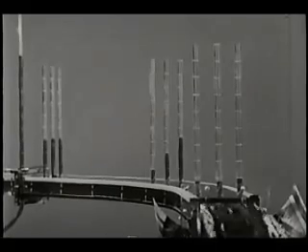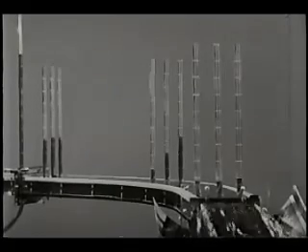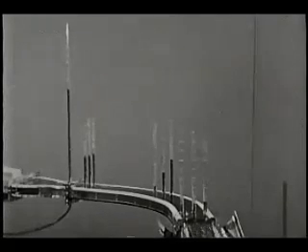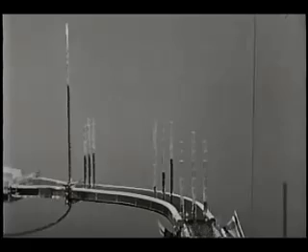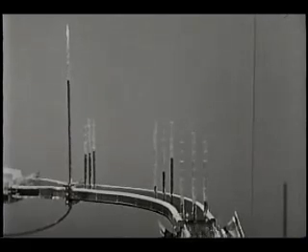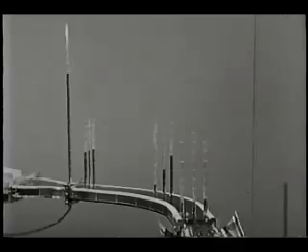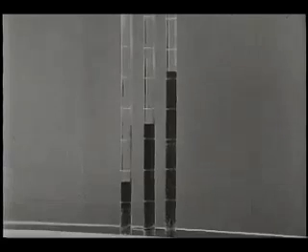This tall tube shows the stagnation pressure in the large upstream settling tank. The difference between this stagnation pressure and the static pressure at the upstream tubes gives a dynamic pressure of about 11 inches of water. At the middle of the bend, there is a pressure difference normal to the streamlines of about 3.5 inches of water.